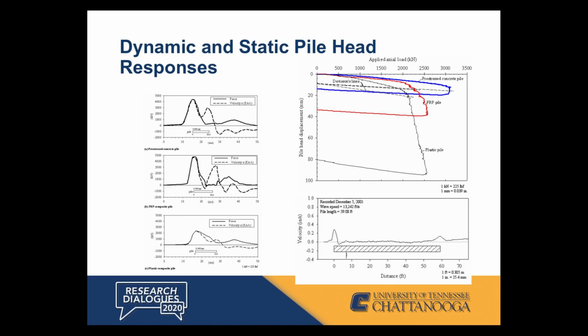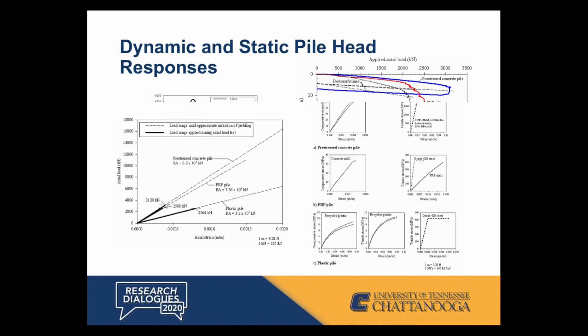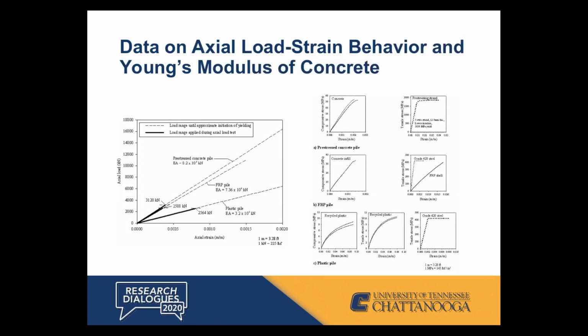the FRP composite pile and the plastic composite pile. But this study is going to concentrate on the pre-stressed concrete pile, and we see the pile head response to that, both the force and the velocity times impedance response to it. We have also had data on the axial load strain behavior and Young's modulus of concrete, which are obviously two related, and that's where we ran into our first difficulty.